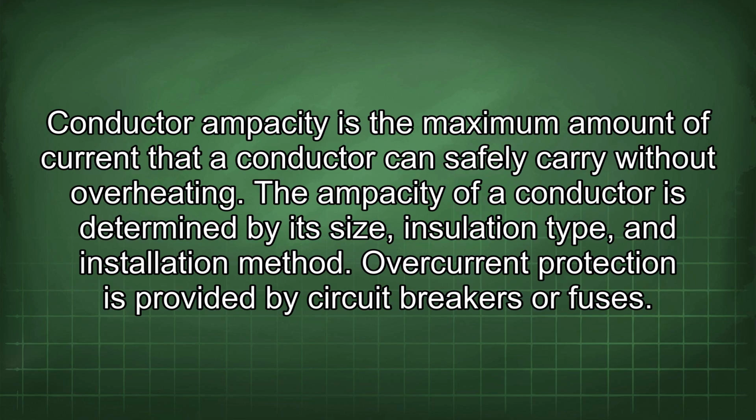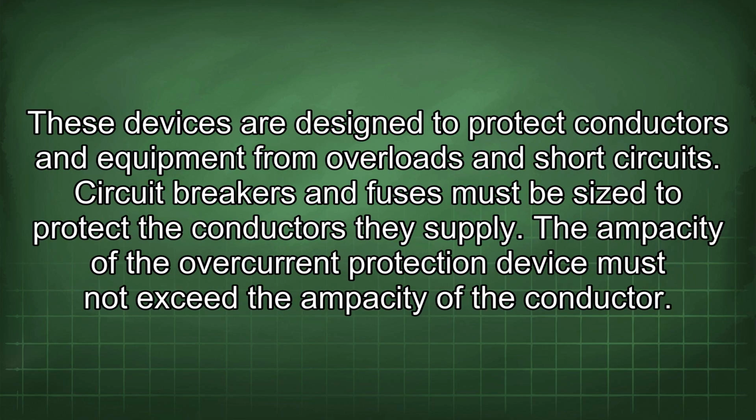Overcurrent protection is provided by circuit breakers or fuses. These devices are designed to protect conductors and equipment from overloads and short circuits. Circuit breakers and fuses must be sized to protect the conductors they supply. The ampacity of the overcurrent protection device must not exceed the ampacity of the conductor.